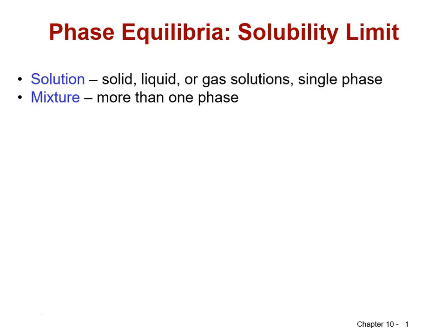In many cases that can be achieved by very slow cooling in a furnace, slow pressure changes, mixing components very slowly so that heat can escape, etc. So for our purposes, for heat treatment in metals, that will usually be accomplished simply by cooling slowly.